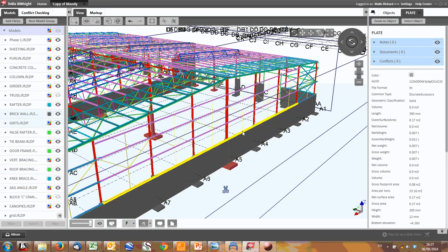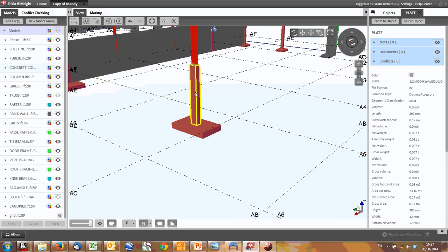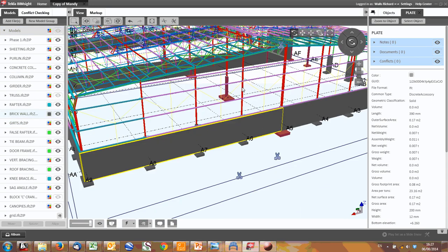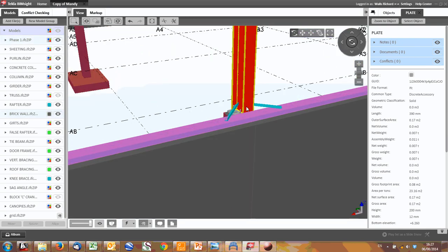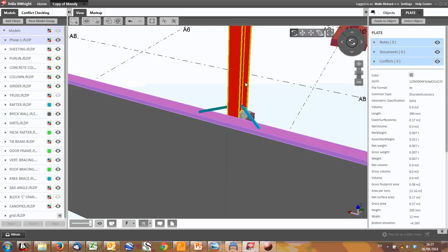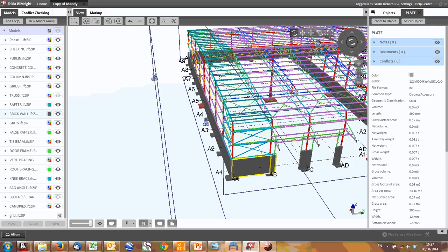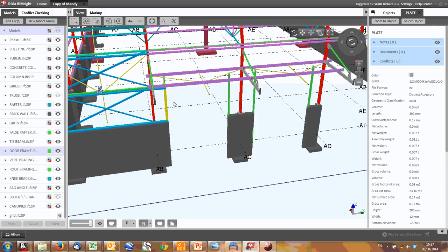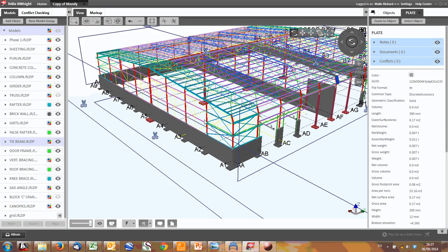Then we've got our walls all the way around outside. We've got our foundations, our bases, and our columns. Our columns sit on plinths, made of concrete, that support our columns. Our base plates link the concrete to the steelwork. These are knee braces that prevent the warping of the columns. And those are the main items of the structure. There are other items such as door frames, roller shutter doors, the canopies on the front. But at least that for now is the main items.